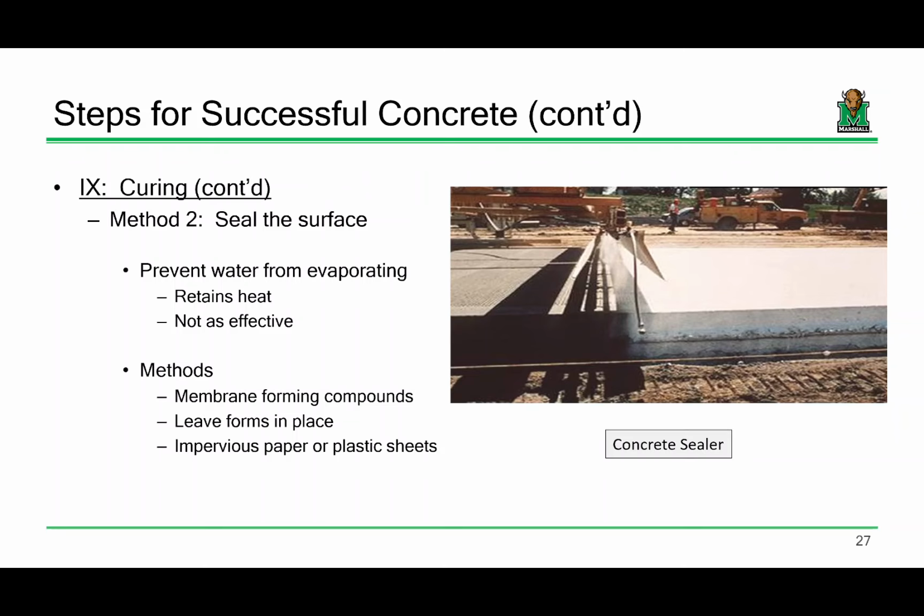You also might find a sealing compound placed depending upon the environment. It does prevent the water from evaporating, which is great. But sealing compounds can also retain some heat, which may or may not be all that great. It just depends on the environment that you're in. It works. It's simple. It's fast for sealing and for trapping in that moisture.